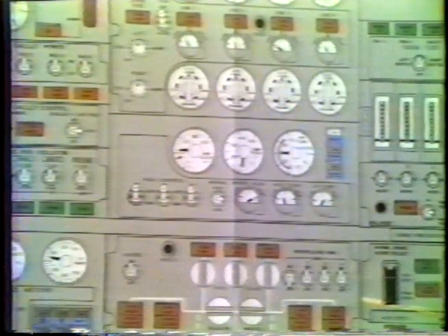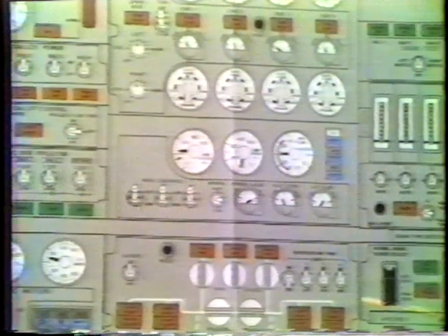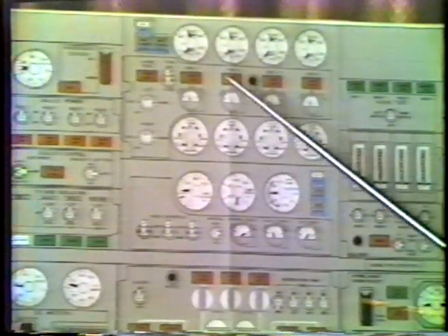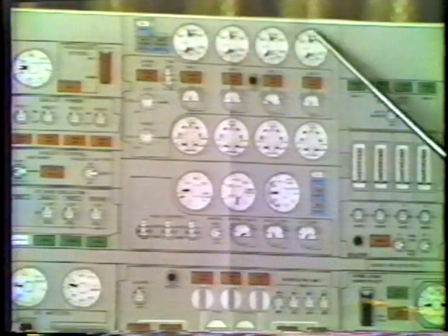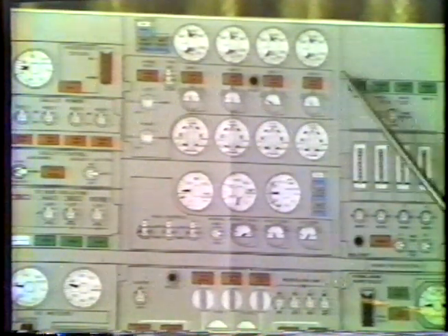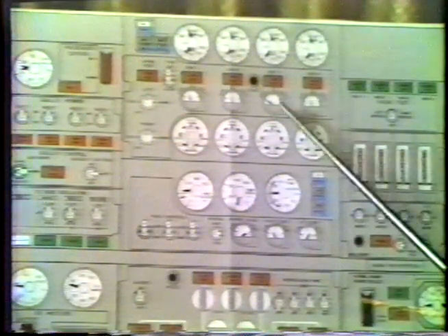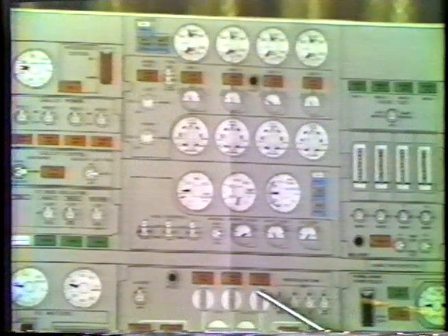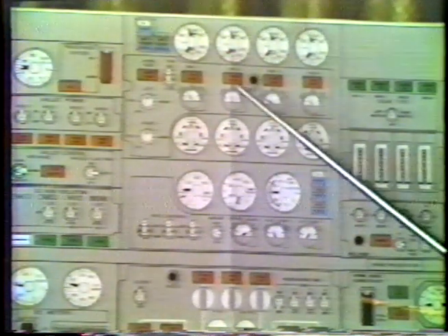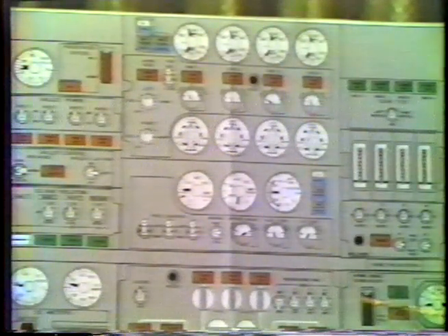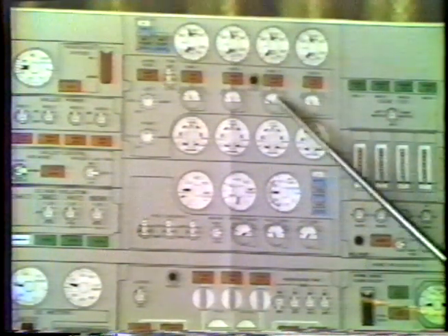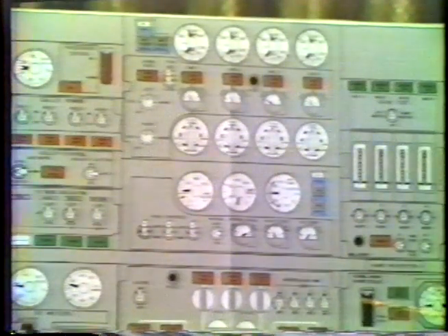Now, since the other areas require slightly warmer air, the trim air will move from full cool to modify that conditioned air for those particular areas. At all times, one of the 4 trim airs should be in the coolest position, and that's the one that's controlling the packs. Generally on the ground, the cockpit is the controlling zone. In flight, zone 3 starts out as the controlling zone, and it could switch to another zone, probably zone 2, on a long flight.